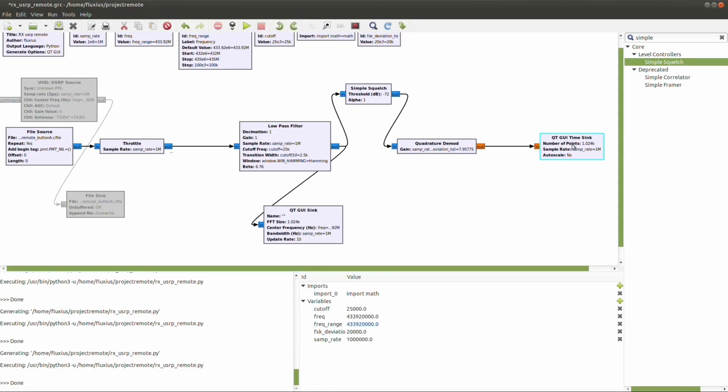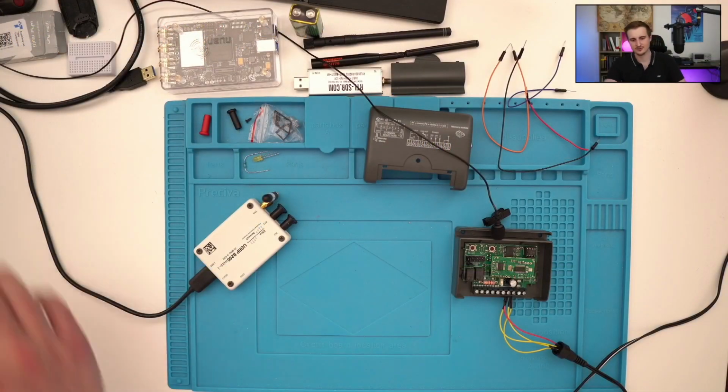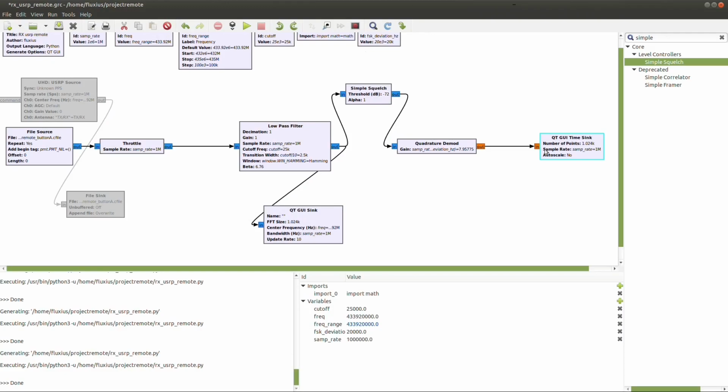So after the demodulation, we need something very important. As you may remember, the signal is always sending a lot of repeated symbols over time in order for the receiver to synchronize with this signal. So we also need to remove all the samples that represent the same symbol and get only the initial bits.